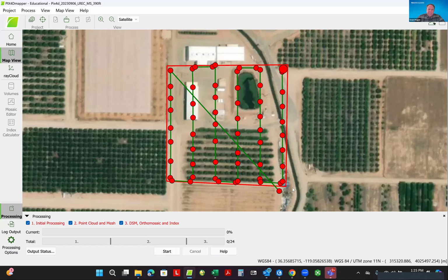But something to note is that anything outside of the area under the images, the nadir positions below all of the images, is going to have spectral and spatial distortions, because you're only going to be seeing those positions at an angle, in the panoramic distorted area from the footprint. Think fisheye, the fisheye area of these outside edge images. So that's why you might set your limiting area. For now, I'll just remove that. I don't need that on there.